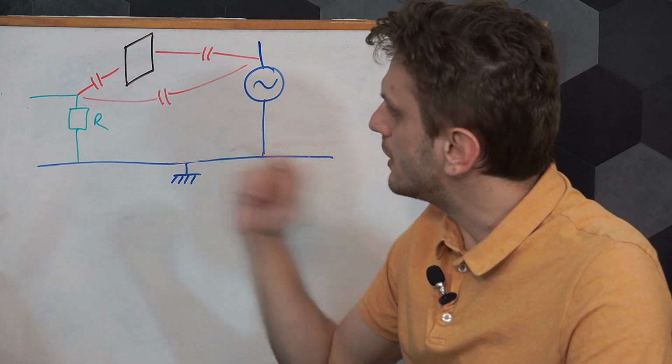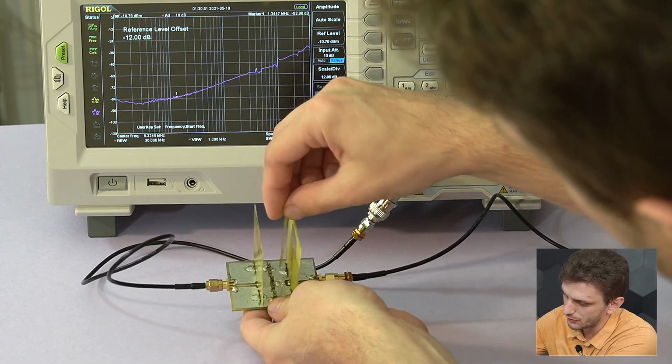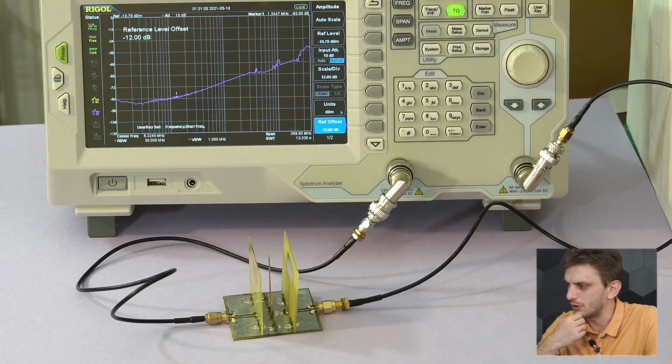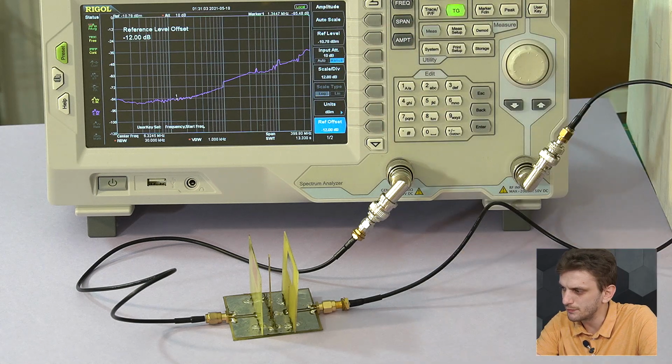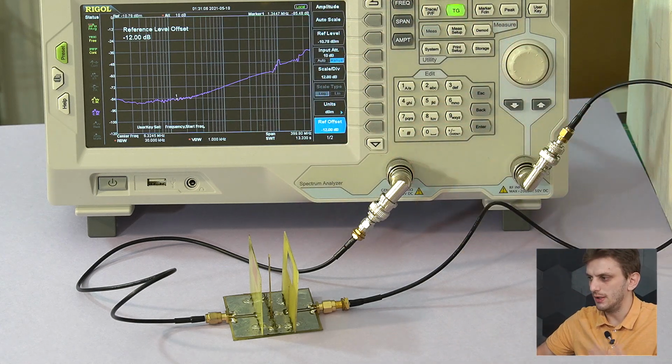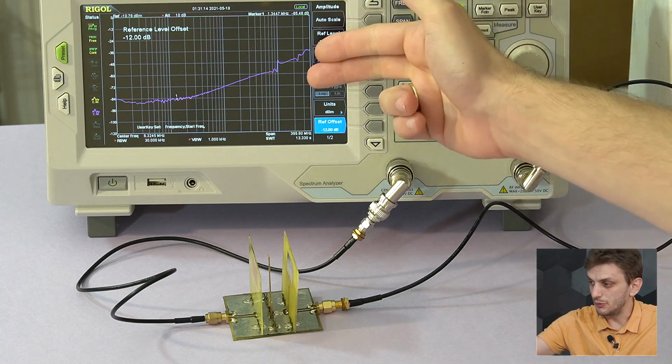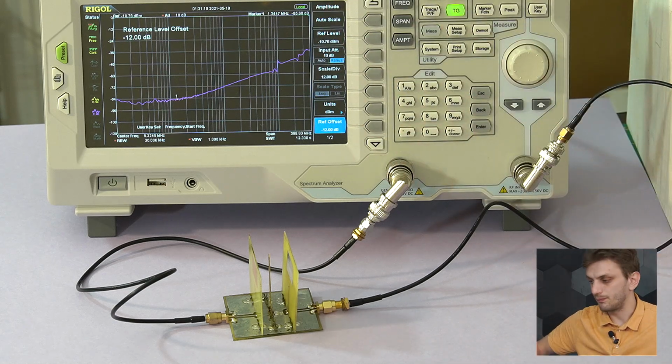So what would happen if we would ground this thing? To show off this effect, first of all, I'll be adding a single very thin ground wire that will be placed in between the two plates. So this will be the closest conductor to the noise source, much closer than our sensitive circuit on the other side. So if I insert this into the ground holding clip and we watch our measurement get performed, we can see that there was a significant drop. So our sensitive circuit is not perfectly protected, but we see a lower coupling than before.